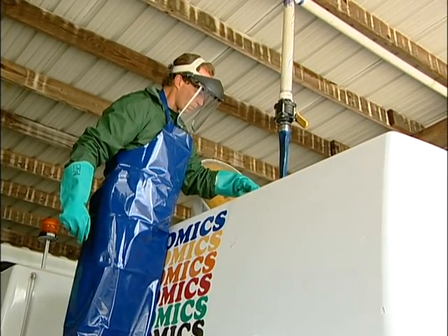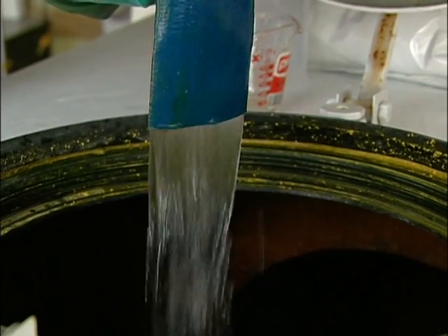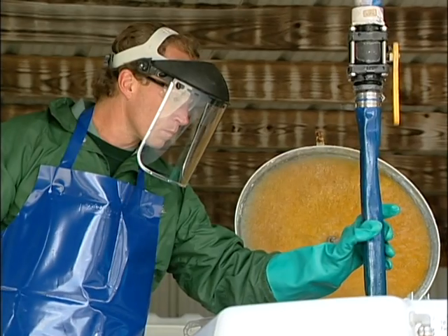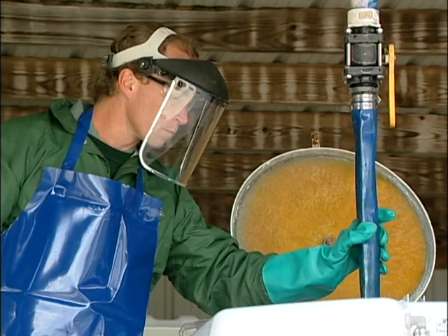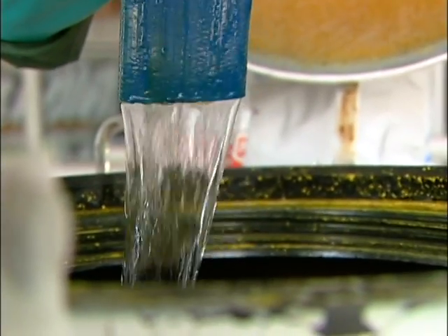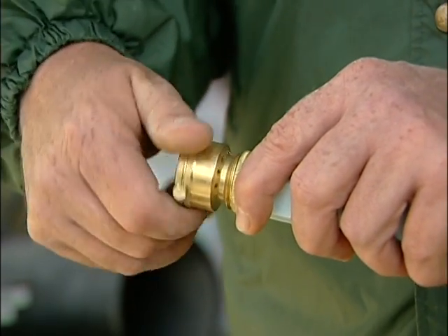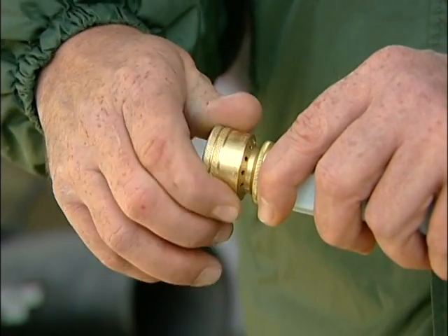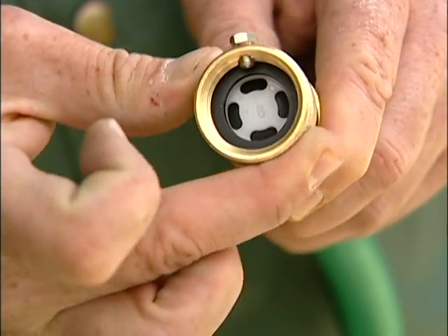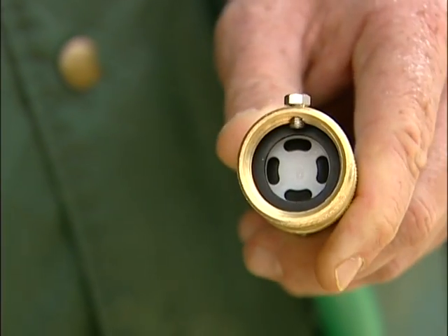Pesticides can be siphoned back into drinking water supplies if there is a decrease in water pressure and the end of the hose is below the water level. Watch the water level carefully to prevent spills caused by overfilling. Hoses used for filling pesticide sprayers should be equipped with a backflow prevention device. This prevents the pesticide from being siphoned back into the water hose.